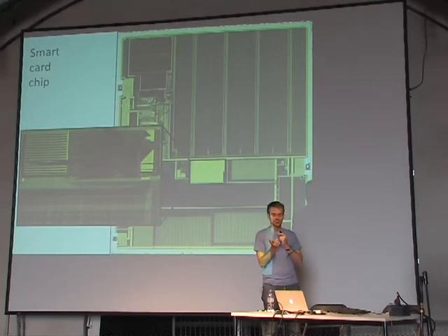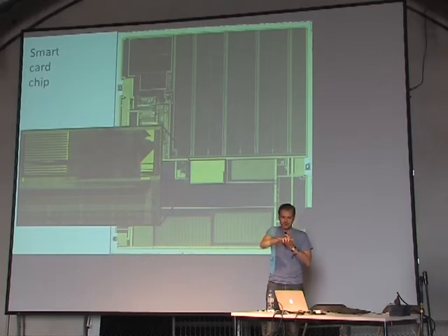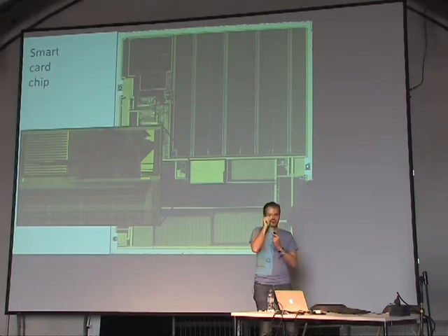So I understand what he's using is polishing paste. So the finest polishing paste you can find on a rotating surface. And then he glues the chip to a block of plastic and puts the chip on this rotating polishing paste for a couple seconds, maybe up to a minute, and then one layer is gone. Chris Donofsky, on the other hand, does this just with his finger. So he puts the chip on his finger, puts it on a rotating disc with polishing paste. He kind of has a feel for when it's right, a little magic, but you know,